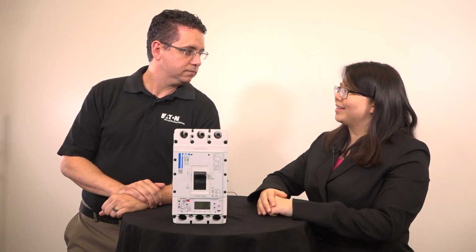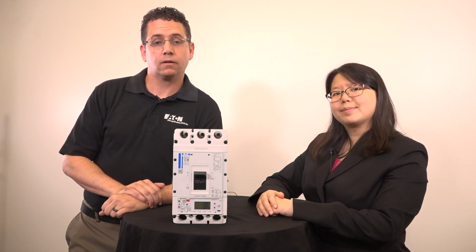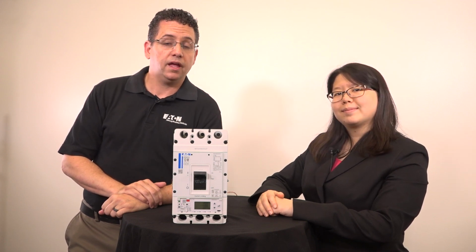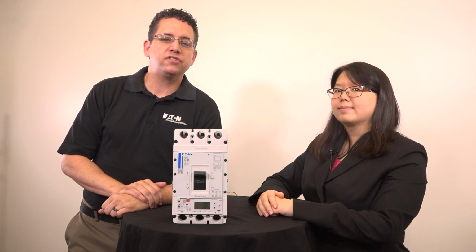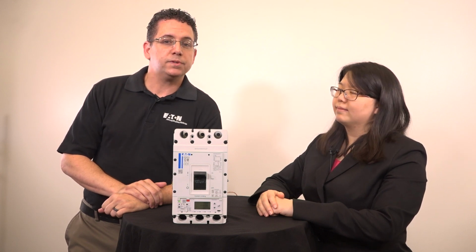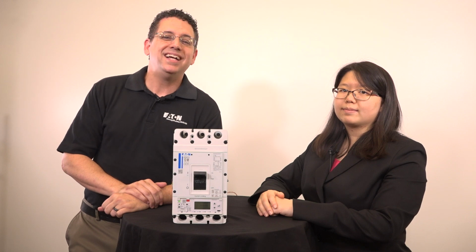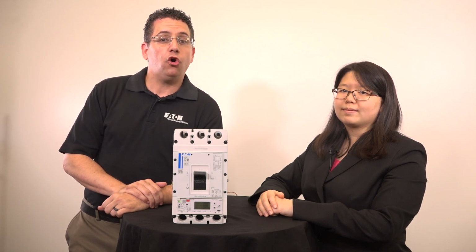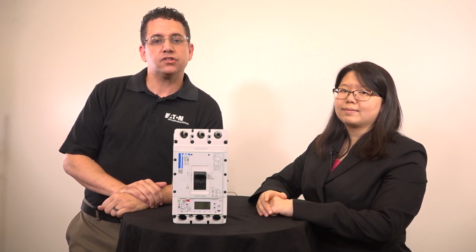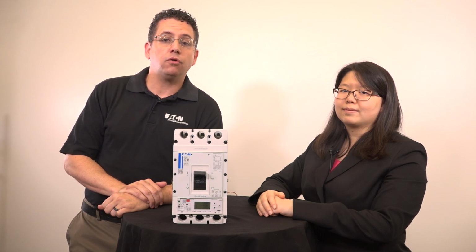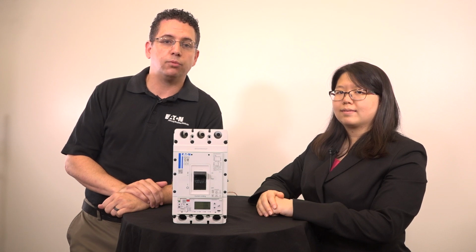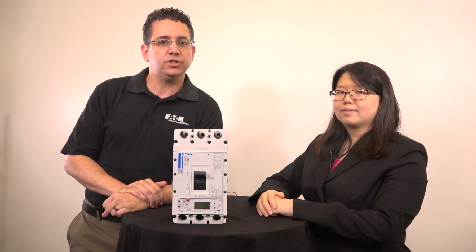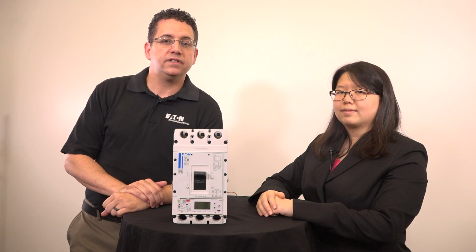Why don't we want to reset the diagnostic data in our breaker? Every breaker operation, every overload, every fault puts wear somewhere on your breaker. Depending on the specific conditions present during each, every event has a different impact on the overall life of your breaker. The PXR electronic trip units have a unique feature called breaker health. Breaker health captures the impact of these events over the life of the breaker and uses an intelligent algorithm to predict how much more effective life it has remaining. This helps with proactive maintenance and resource planning.